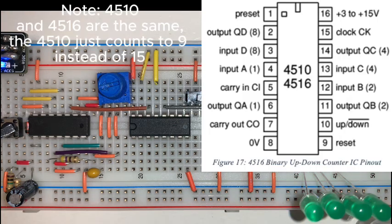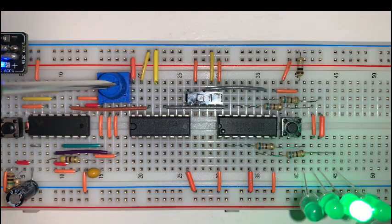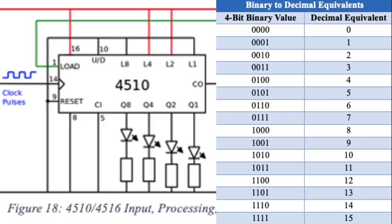The 4516 IC drives this, taking the divided by 10 clock signal from the decade counter, meaning the potentiometer can adjust count speed. The clock signal provides binary coded decimal, or BCD, data, which the chip processes into output signals representing the current count in BCD format. These signals are then sent to the LEDs.